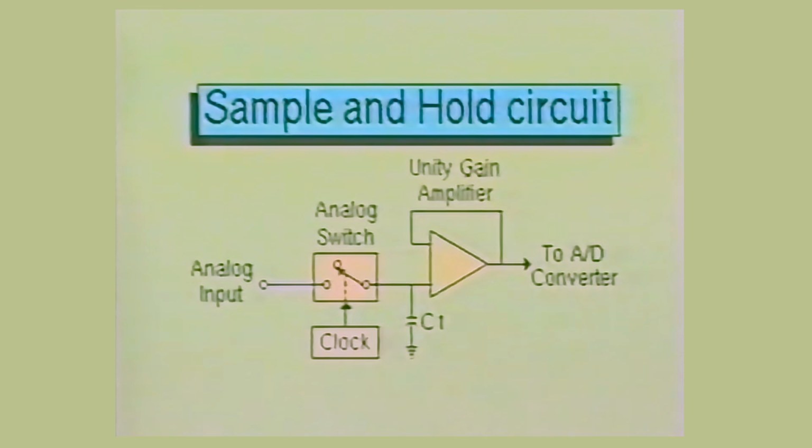As you can see, by using a sample and hold circuit at the input of the AD converter, the quantizing error has been greatly reduced or completely eliminated. This is due to the fact that the input voltage to the ADC stage remains constant during the conversion time period. We will now pause for a short review of the most recently discussed material.